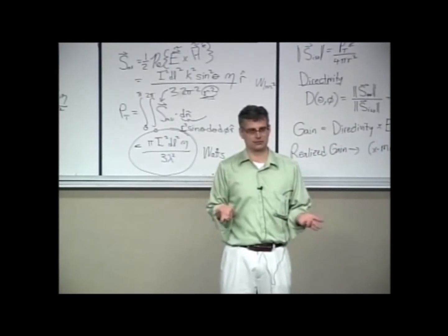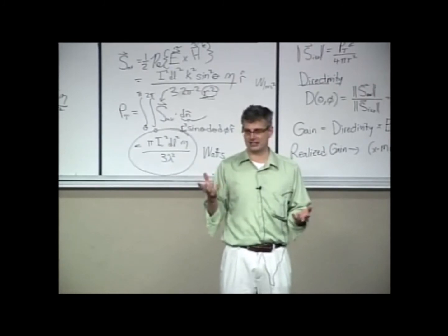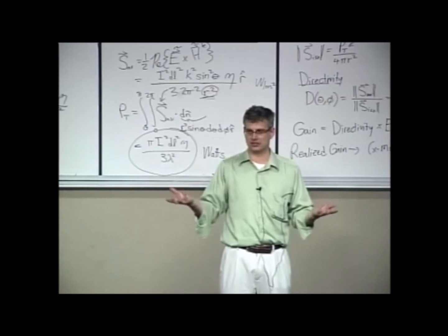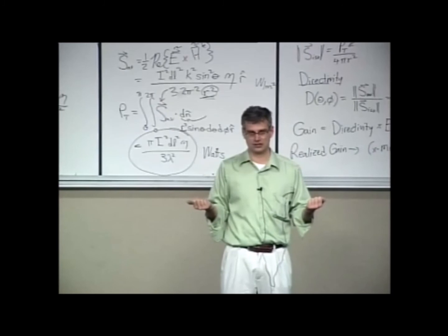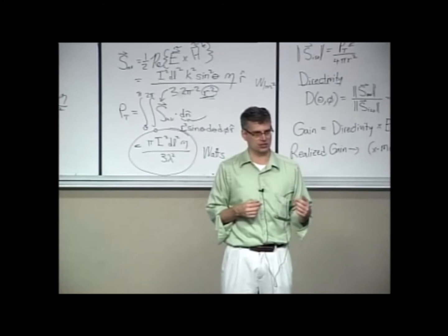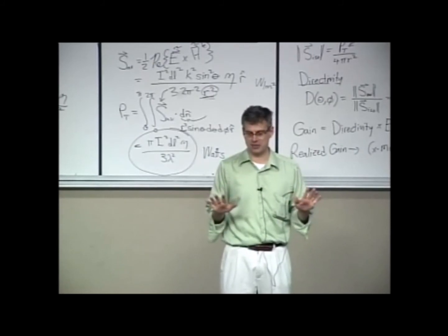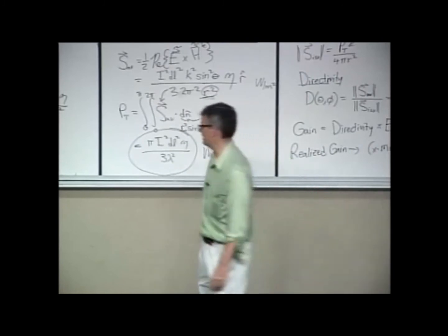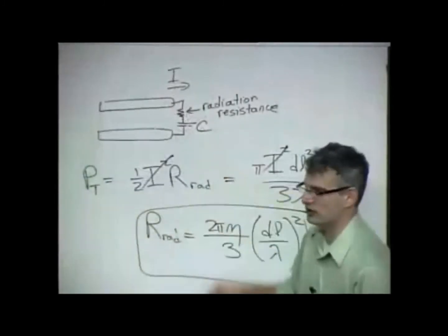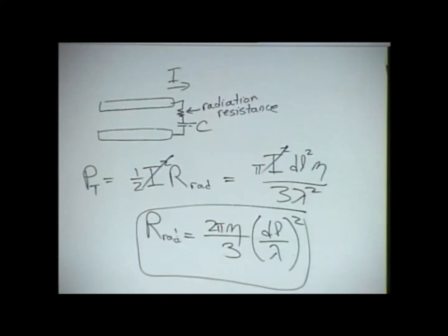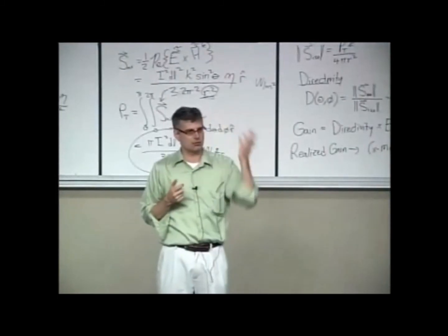You say, well, wait a second. So I've got a very small R and a huge capacitance. Any electrical engineer who's taken circuits knows that you can resonate some of that reactance out of the network and then do some sort of impedance transformation. And those games work well when you're kind of mismatched. But when you're severely mismatched, the first thing you have to do is get rid of this C, the capacitance. Well, that means you need an inductor, right? So I start winding a coil of inductance. What's the problem with inductors?